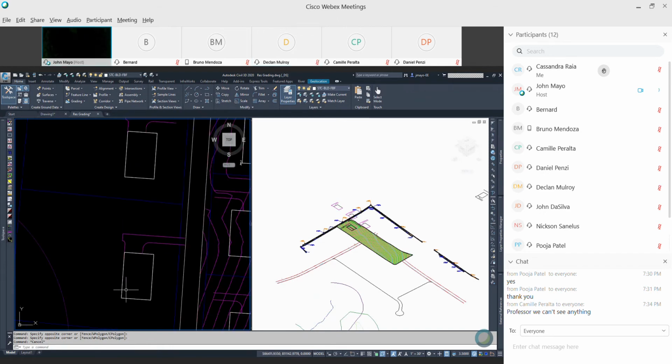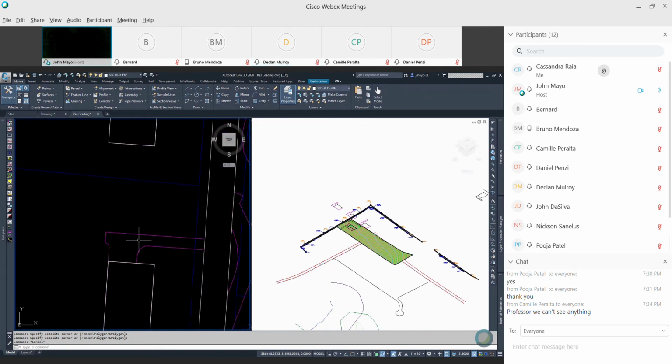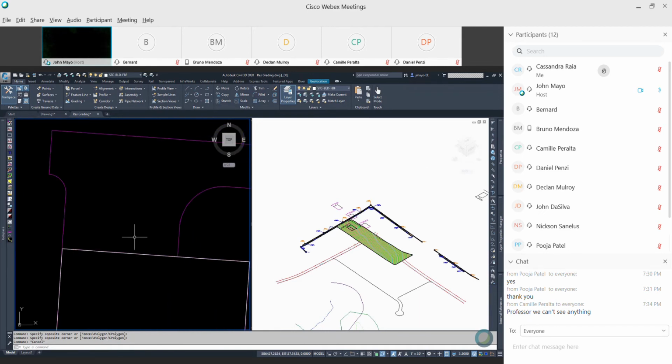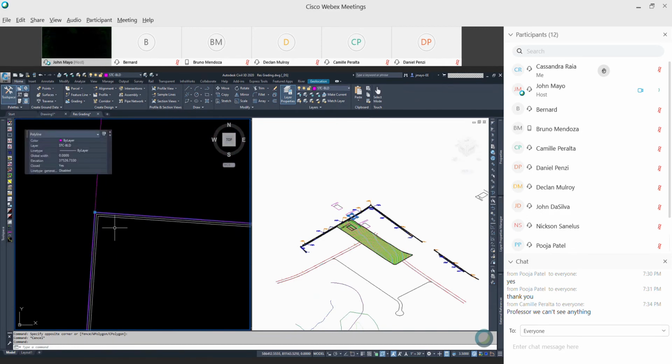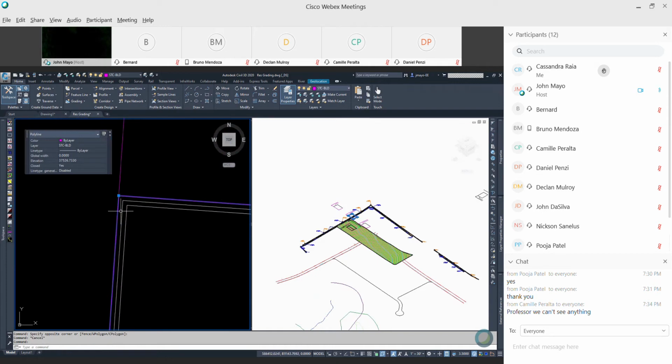So this is the building, right? And did you guys get everything up to that 3 polylines? Someone answer? All right. So each building is 3 polylines. This is the outer polyline. It's the one you drew, and it represents the grade line. This is where the dirt hits the building. Offset that 0.05 units. This is going to be your basement floor. Offset that 0.05 units, and that is going to be your first floor.